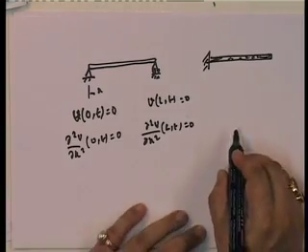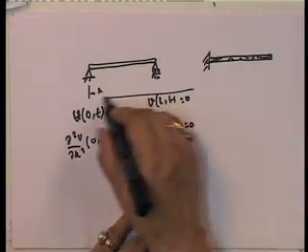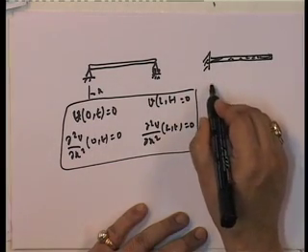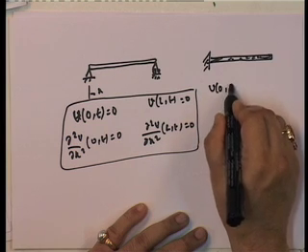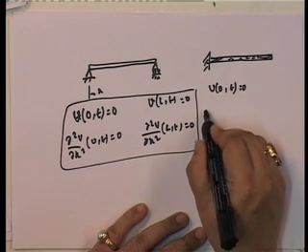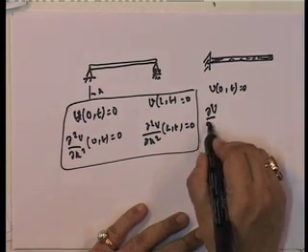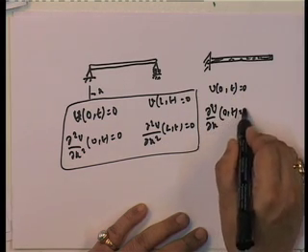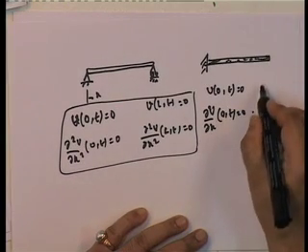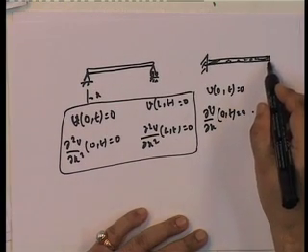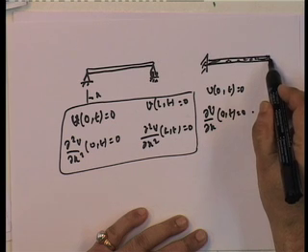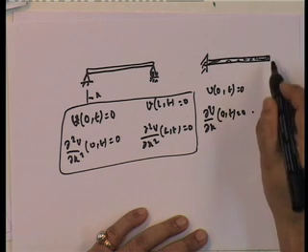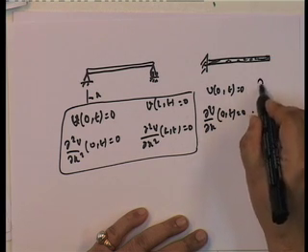What do I get over here? So these are the 4 boundary conditions for this. What are the 4 boundary conditions? Let us see. v(0,t) is equal to 0, and ∂v/∂x, no slope at (0,t), is equal to 0. Here, I know nothing about displacement, displacement can occur. I know nothing about slope, slope can occur, but there can be no shear.